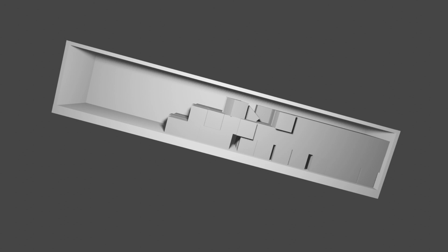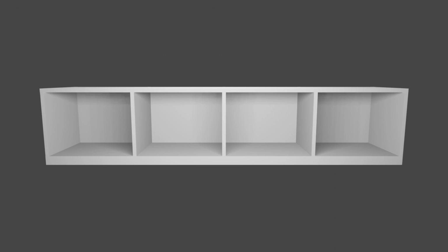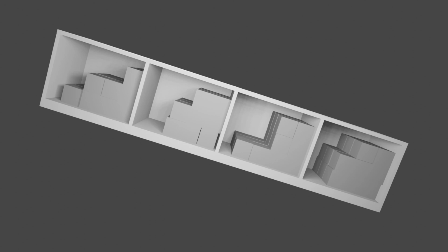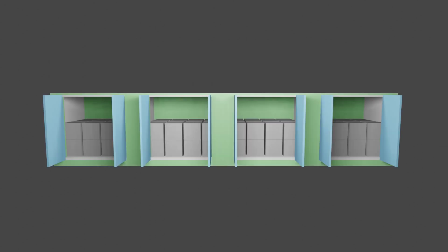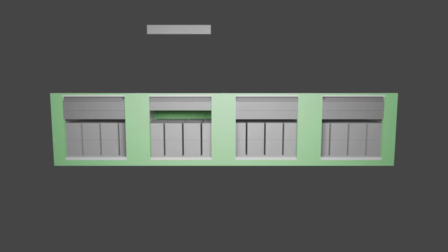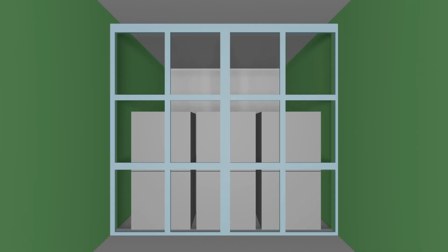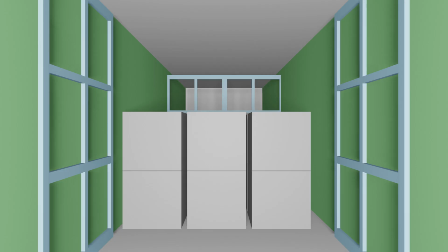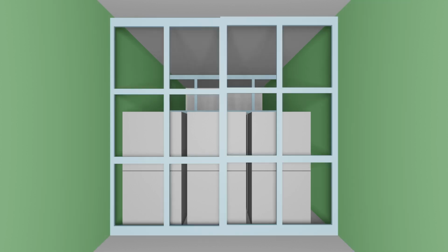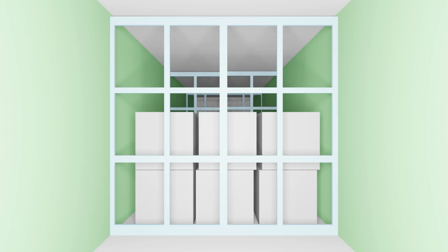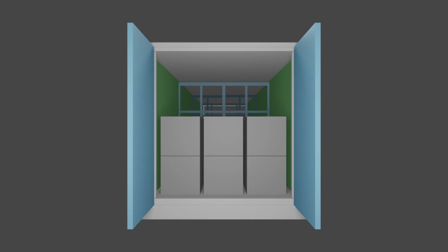The cargo containers would have to be partitioned, either with permanent walls down the length of the container, with the access to the container being on the side of the container, or if you want the access doors to be at the back, as they are with the standard cargo container, there would have to be a series of gates down the length of the container. So some cargo would be loaded, a gate would be closed and locked, and some more cargo would be loaded, another gate would be closed and locked, and so forth, till you get to those last doors on the container, and they're closed and locked, and that would prevent the cargo from shifting.